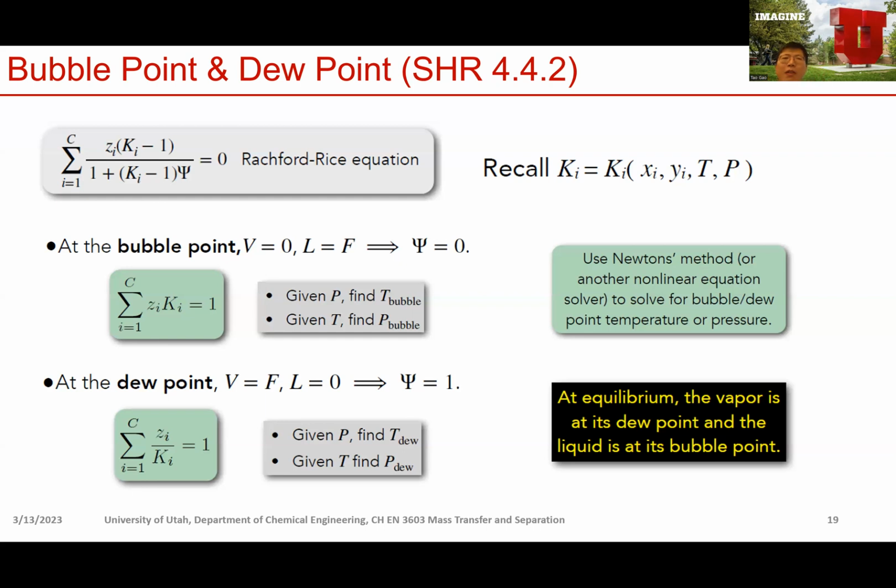In the last lecture we started to talk about multi-component flash calculation. We went through the degrees of freedom calculation, and the degrees of freedom is plus 4, and typically the composition, flow rate, temperature, and pressure of the feed are given.